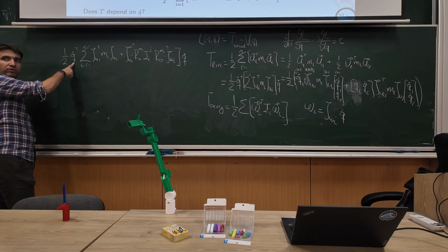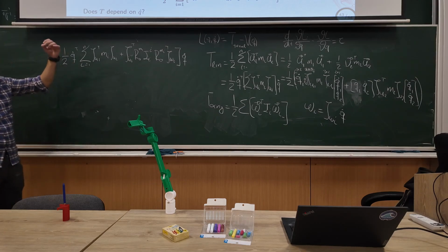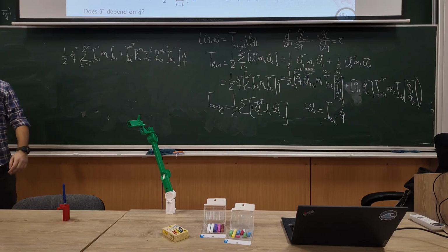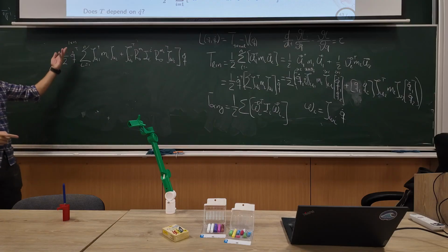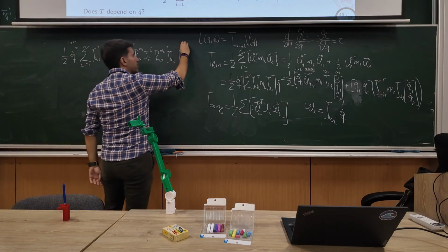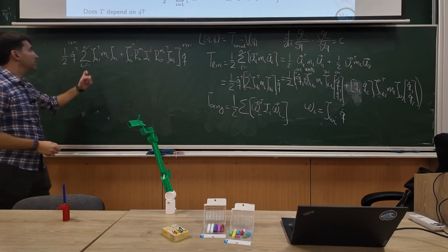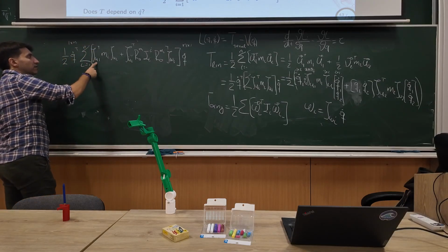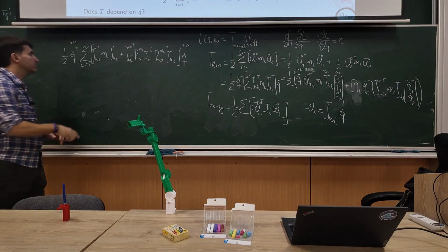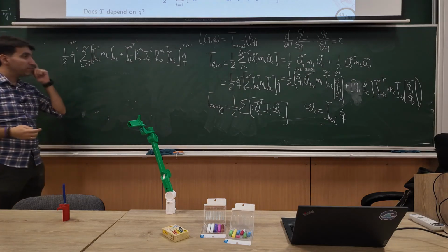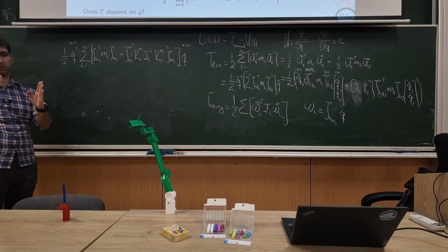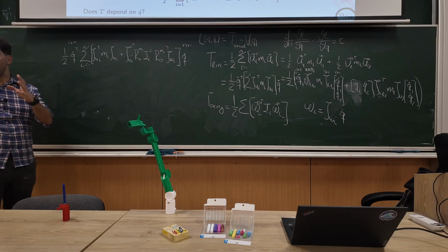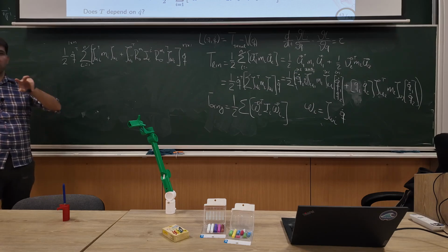What would be the size of Q dot for n joints? 1 over n? 1 times n, because it's transposed, right? Good. And then this will be n times 1. Great. The Jacobian here, this is i. Remember we said that we pad the Jacobian with zeros. The first Jacobian we pad with as many zeros until we have n columns. The second one, the third to nth column will be zeros and so on.